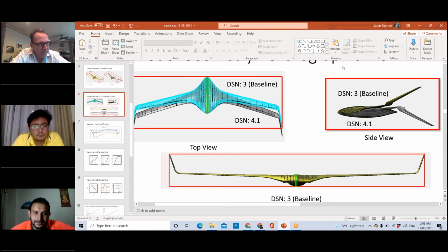Did we talk about propeller normal force before? I think we did. But in any case, it can add some directional stability. It'll add a little pitch stability too. And if it's on the trailing edge of the center line, you can add pitch and yaw stability without shifting the trim point very much at all. You have that option anyway.